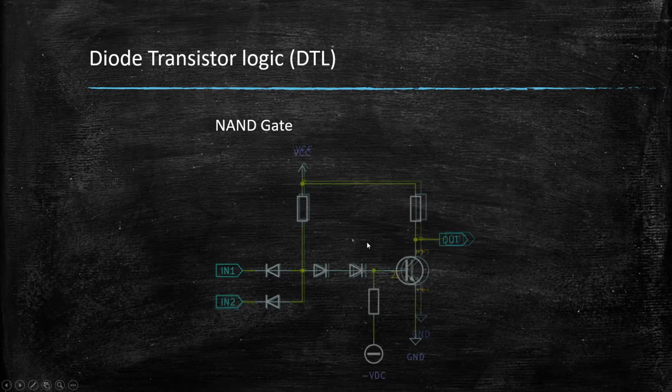However, we can fix that by tying either ground or a negative voltage via a resistor to the base here. And that gives our charges on our base junction a path to discharge. So this will improve our switching time, not increase it, but actually decrease it by quite a bit. However, we are not quite there yet. We can do one better.